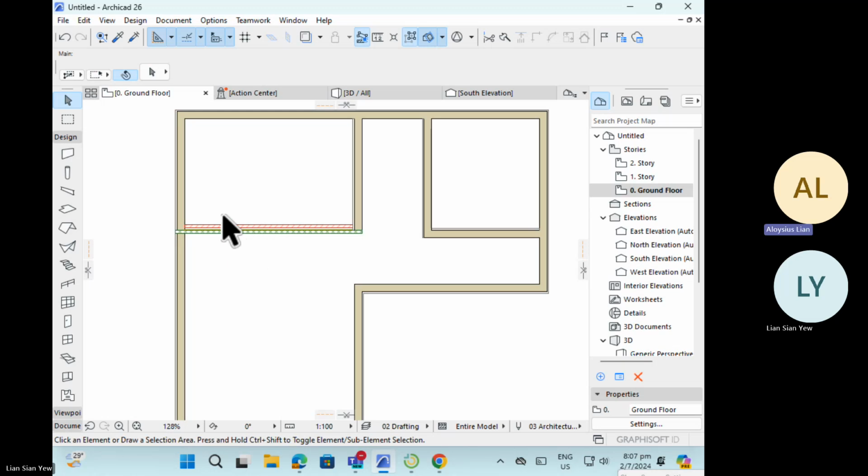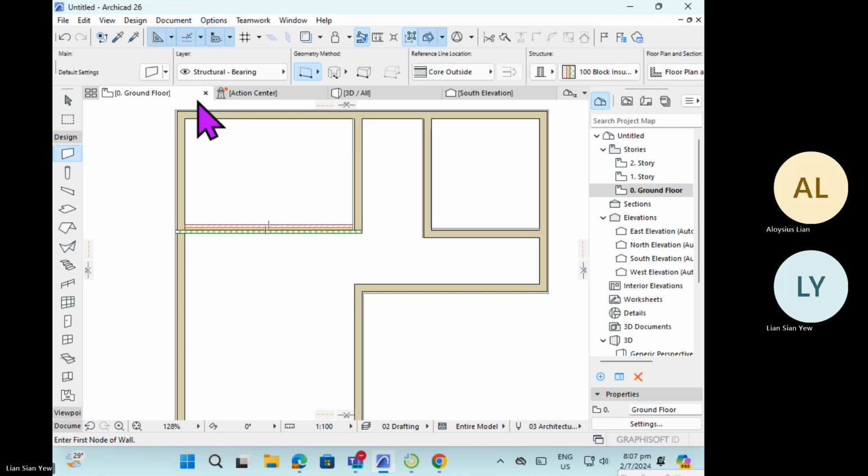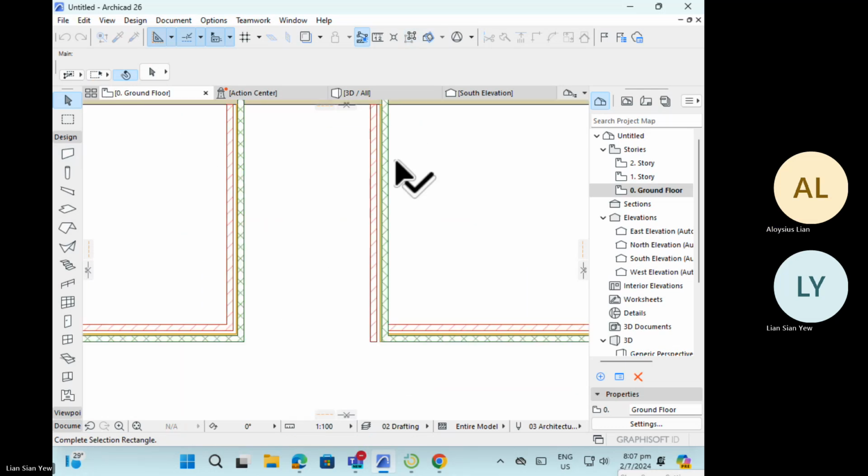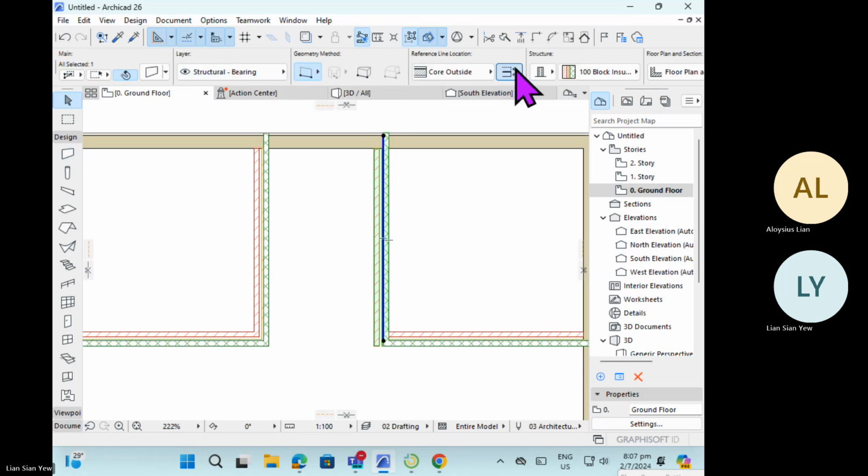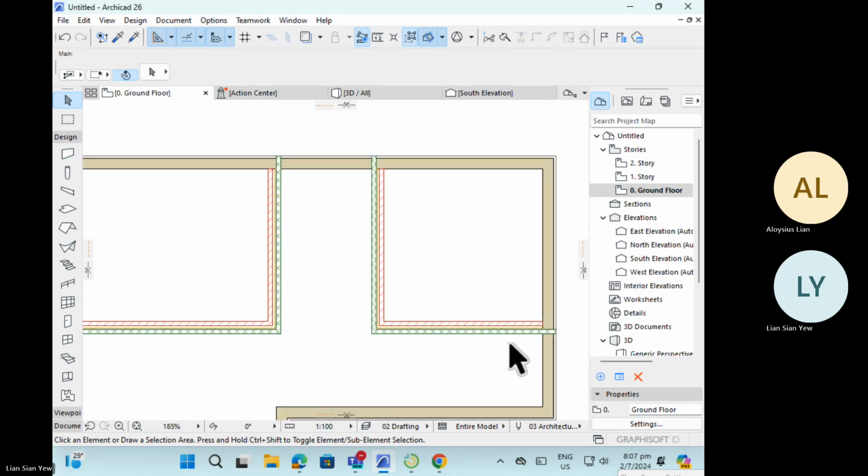And remember just now in the beginning of the lesson, I said that you can pick, right, and apply. So it's here. Okay. So click on this dropper tool. Choose your new wall. And then now click on inject. And you inject to this wall. Similarly, you can inject to all the other walls. Okay.